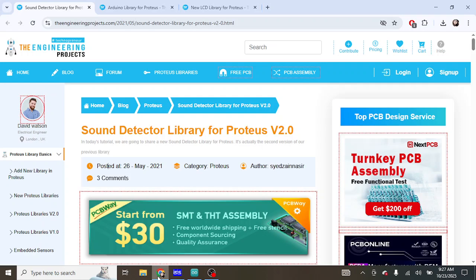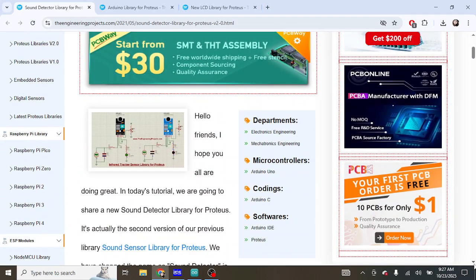Mainly, you will see the sensor has four major pins. The first one is the analog output pin that gives the continuous voltage depending on the sound intensity. The second one is the digital output pin where the signals change from high to low or low to high depending on the threshold value. We also have a VCC for the power and the ground for the ground terminal.